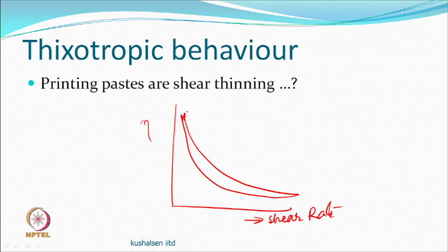Similar is the case of the melt spinning or wet spinning. When polymer solution is pushed through the spinneret, the viscosity around the spinneret and through the hole becomes very low and just passes through that. And after that, of course, there are other processes with which it solidifies. Our aim is different. So, this thixotropic behavior of our printing paste is an important characteristic of the paste. Any polymer which does not give us this also is not so good, all right.